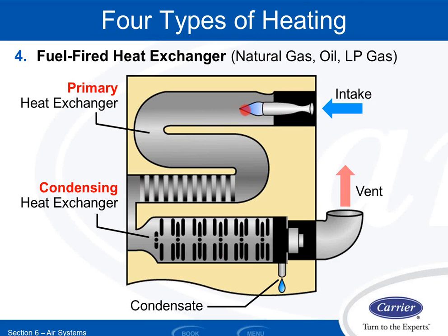So that gas combusts, and I have my exhaust going through this heat exchanger, right? The way my red mouse is going, and then the air from my space is coming up through the furnace assembly this way. Right, so it's seeing the coolest flue gases first. That heats some of the air up.